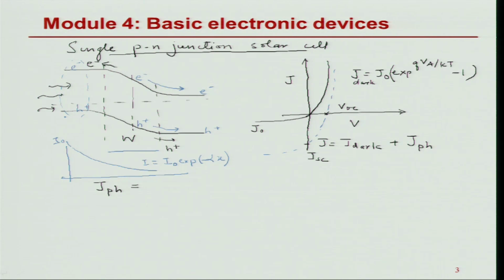So they generally may recombine or drift or diffuse in either direction, but there is a region close to the depletion width, which we define by the diffusion length of the minority carrier on this side. Similarly, there is a region close to the depletion width, which we define by the minority carrier diffusion length on the n side.